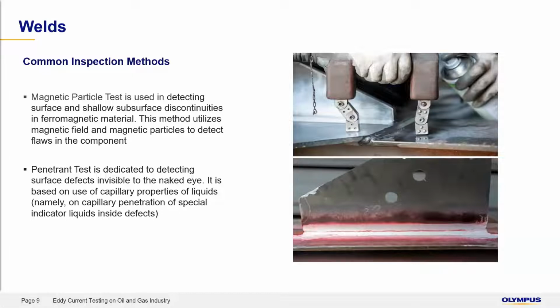Magnetic particle testing involves using chemicals that contain small magnetic particles, either fluorescent or colored, as well as using a magnetic yoke. The magnetic particles are dispensed by means of an aerosol can in between the legs of the yoke while the part is being magnetized. Presence of a defect will distort the magnetic flux in the material and cause magnetic flux leakage around the flaw. This flux leakage can then be displayed when the magnetic particles accumulate and build up around it. Thus, a defect such as a crack is indicated as a line of magnetic particles on the surface.